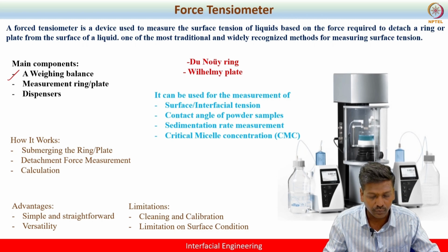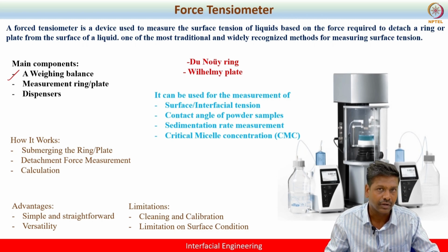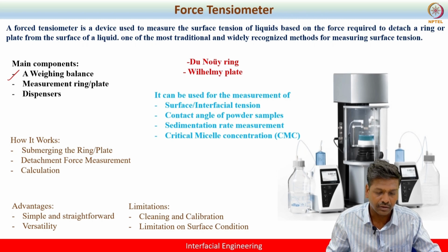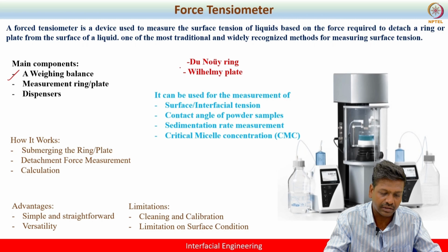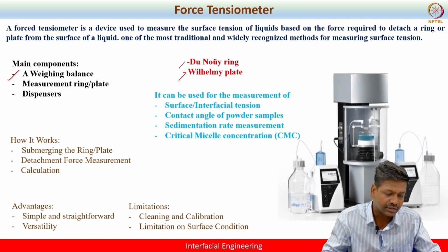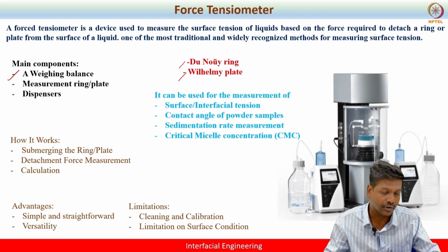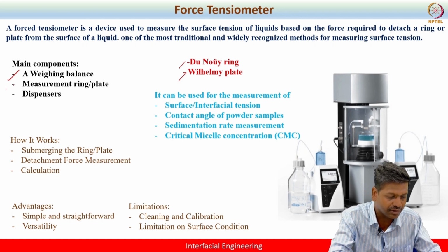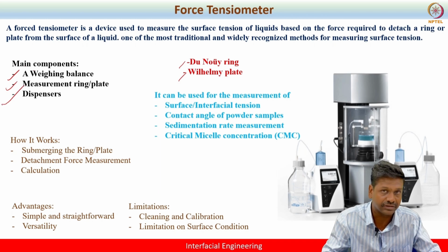The force tensiometer uses the Du Noüy ring method as well as the Wilhelmy plate method. Often these two methods are used whenever you want to measure the interfacial tension of various liquids. It consists of three important key components: the weighing balance, the measurement ring or plate, and the dispenser, right?